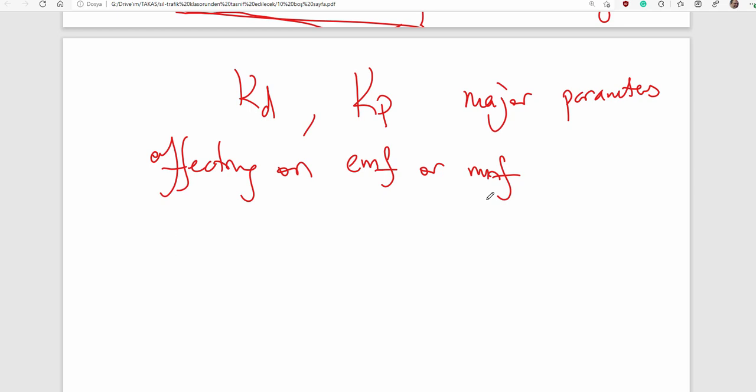But when you make energy conversion, in fact, those two come together. We always generate those two together when there is an electric energy conversion. For example, in a generator, you want to generate an EMF, but after an electrical load is applied, there is an electric current, so electric current will produce MMF.